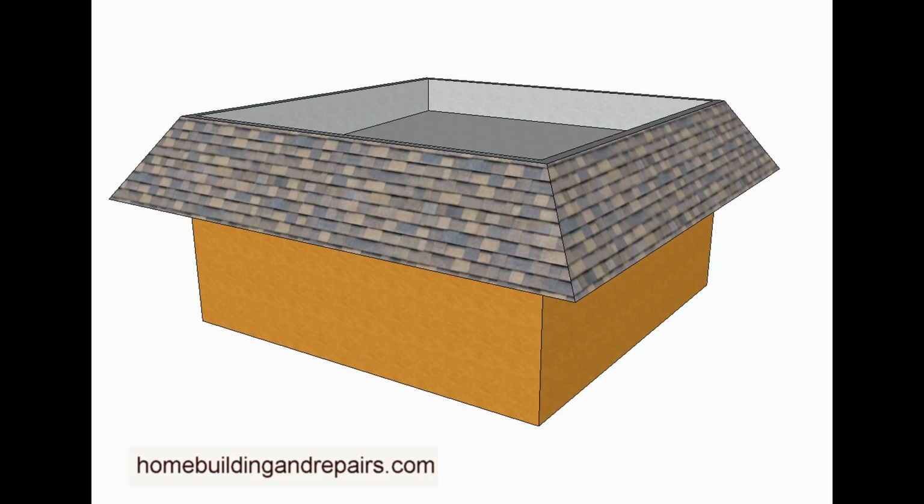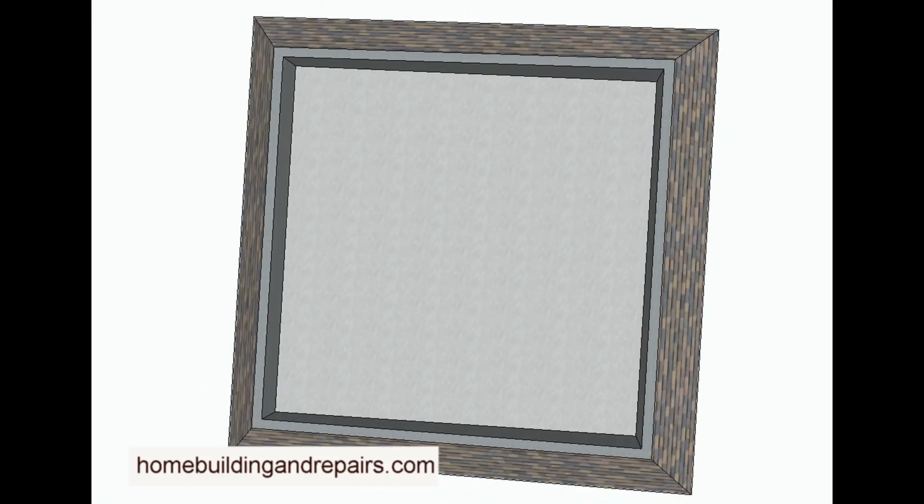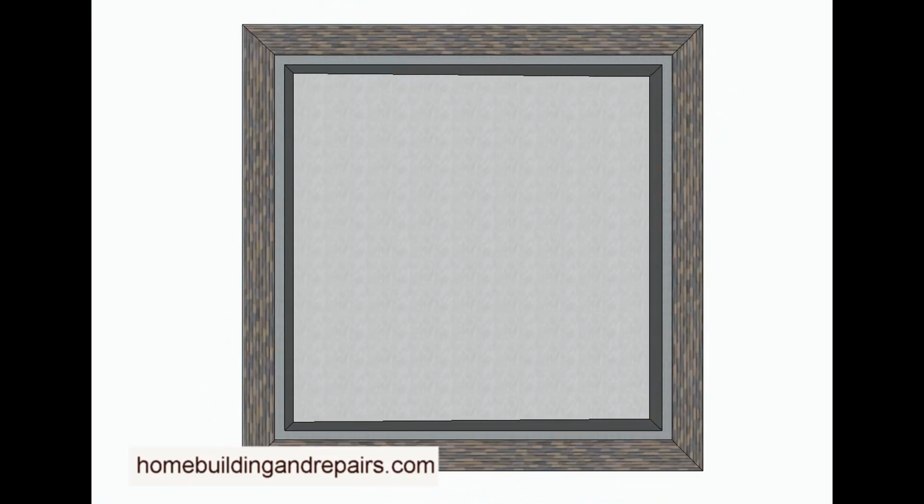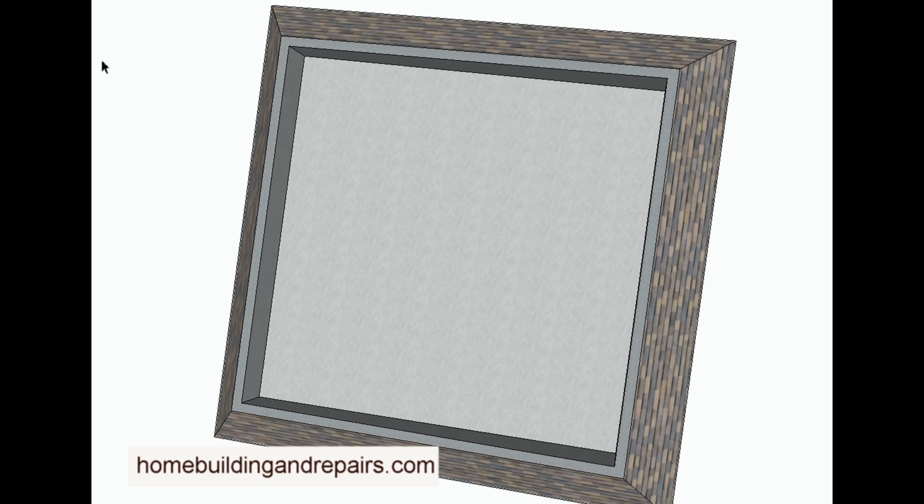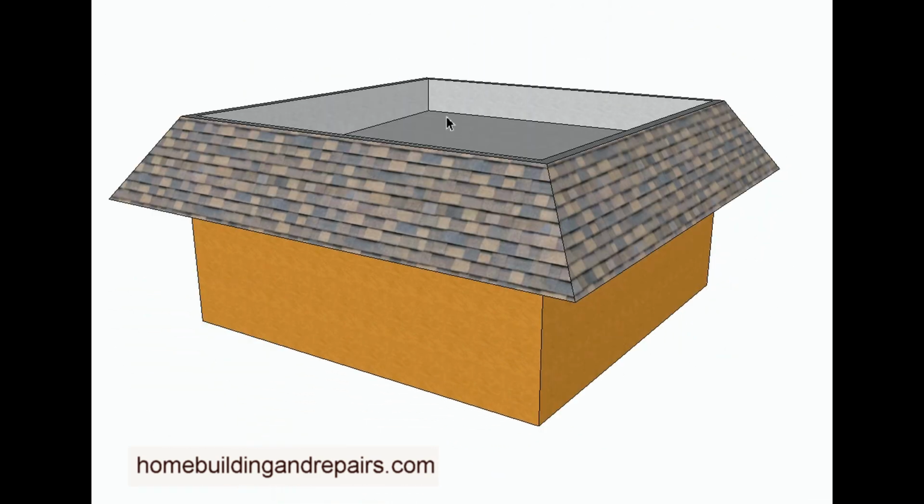It's actually something that we've built, and you see them a lot on commercial properties. You know, they can build something like this and hide the air conditioning equipment on the roof. Works out good for something like that. So again, a Mansard roof, the definition of it is it will come up, it'll have a slope, and then you'll have another slope, kind of a break point coming off, and then up to a flat area or something like this. But I'm going to choose this design because it is the most common one that I have seen.